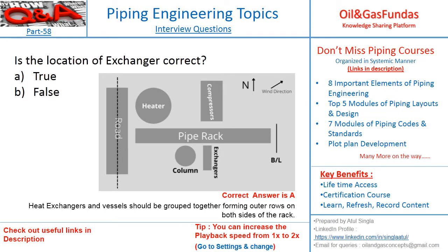So the correct answer is A. This is correct. Now heat exchangers and vessels should be grouped together forming outer rows on both sides of the rack. Okay, so maybe this exchanger, if it is placed on this side, that is also correct, but most of the time these heat exchangers will be having a bundle removal. We need to remove the bundle for maintenance, so that should be towards the road. So that is one aspect which is fulfilled here.